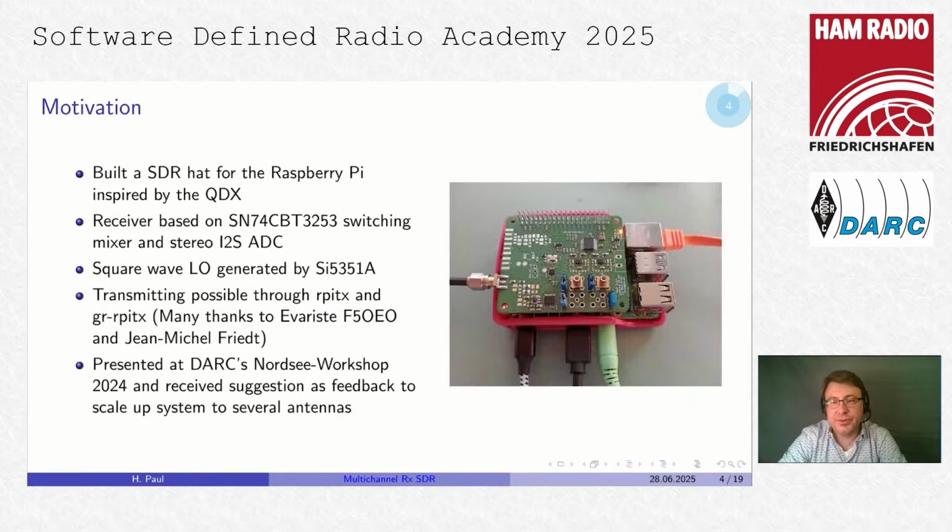So the motivation for this project. 1.5 years ago, I developed an add-on for the Raspberry Pi, which is loosely based on the QDX, or better say, inspired by the QDX. It's a switching mixer receiver with a stereo ADC for digitalization. And